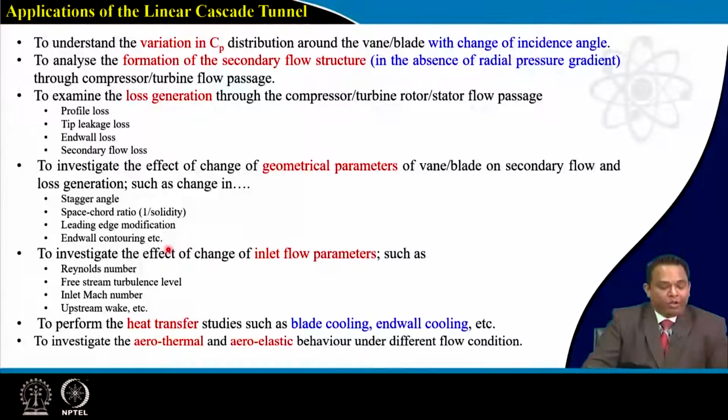We can also investigate the effect of inflow parameters like change of Reynolds number, free stream turbulence, inlet Mach number, upstream wake effect, all those things that affect the performance of an axial flow compressor. So before making a design, people do all this kind of study using the linear cascade tunnel.